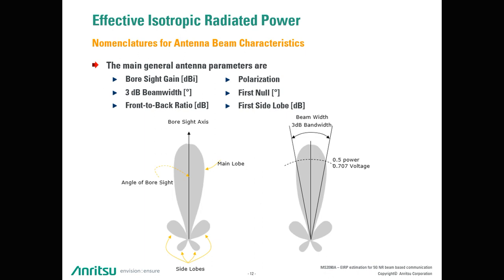The antenna's power gain, or simply gain, is a key performance number which combines the antenna's directivity and the electrical efficiency. In a transmitting antenna, the gain describes how well the antenna converts input power into radio waves headed in a specified direction. The gain is referenced either to a dipole, called dBd, or to an isotropic radiator, called dBi. Due to the fundamental gain of a dipole, the dBd figure is always 2.15 decibels larger than the dBi figure.